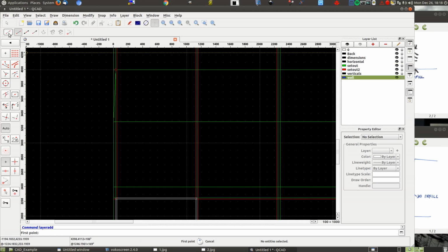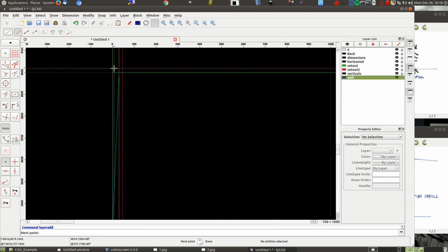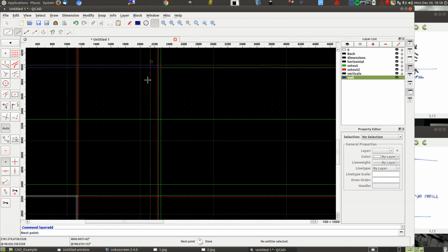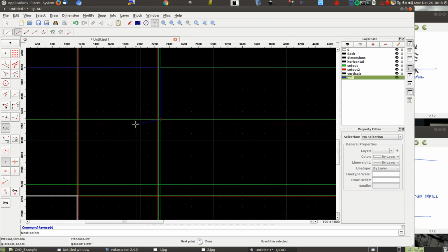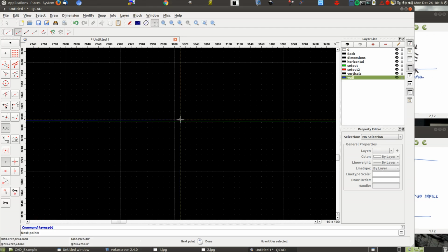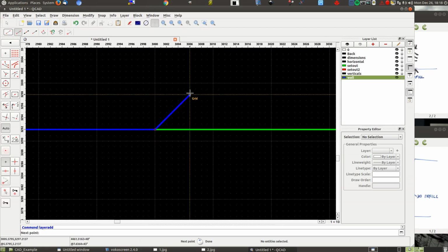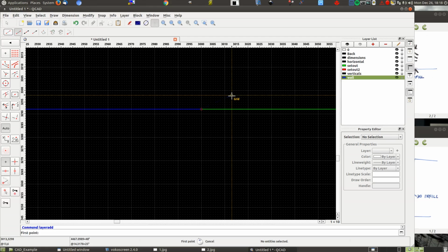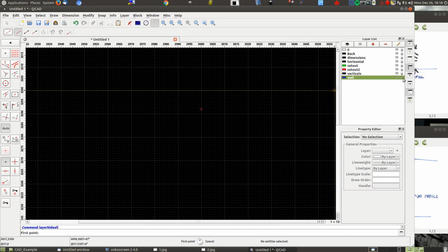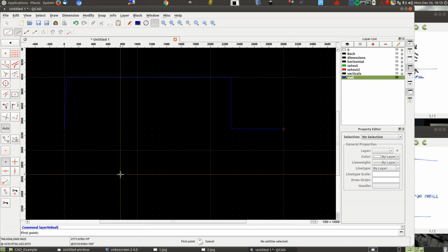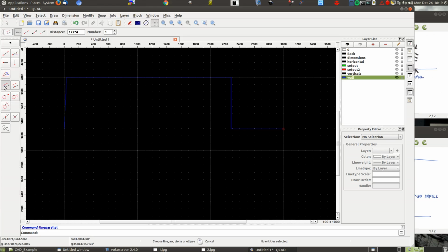Okay, now we're still on the line type that I'm looking for. I'll go here to here. Intersection it's picked. To this intersection. To that intersection. Across randomly to maybe, okay, I'm zooming in until I get a grid line that'll do the job. Okay, so that's that. I'm going to turn everything off, so only the wall is showing. Now that isn't much of a drawing for us to understand, so let's just draw some parallels to that. I'll pretend the wall's 100mm thick, doesn't matter.